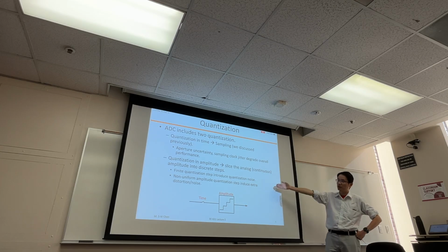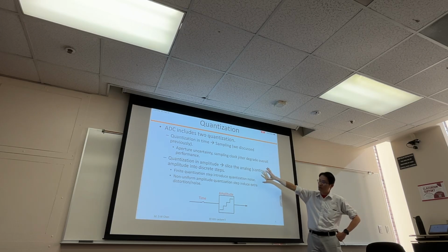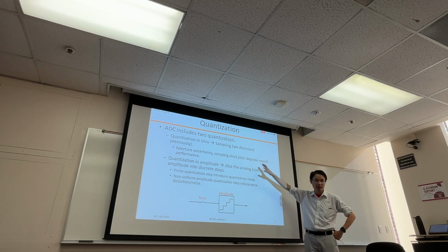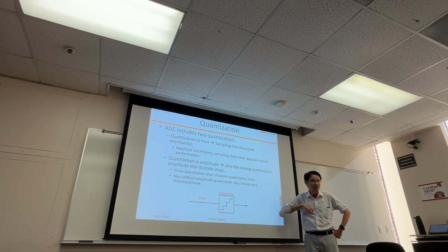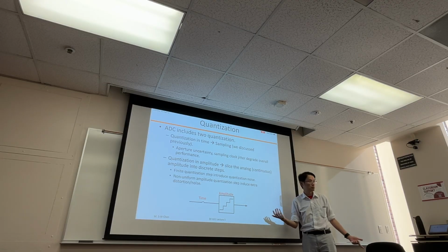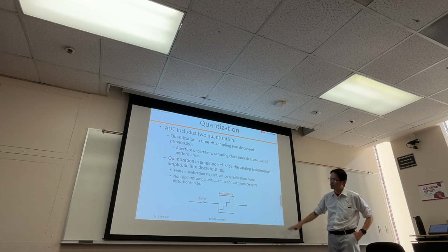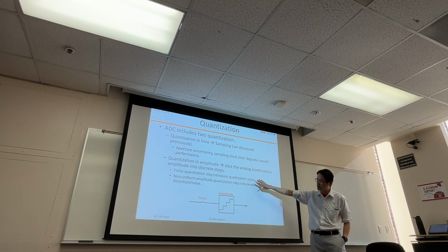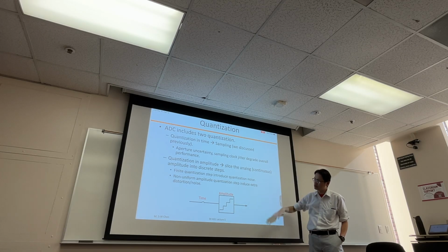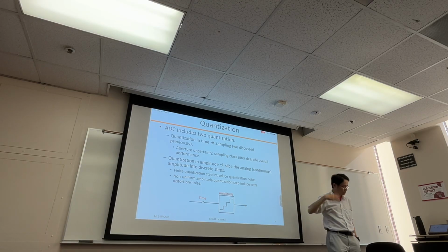And I'm actually done. This ADC is just as simple as that. Whoever can slice, or basically quantize, in amplitude and also in time in a very accurate fashion, you win. You win big time. You can sell your product much more expensively, and your overall system is going to perform better in most cases. So that's basically what we're going to go into. We're going to analyze the impact of those quantizations, and some of those quantizations can be non-uniform. So what is the impact?